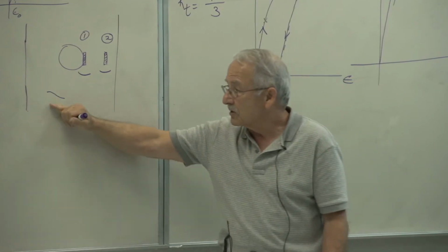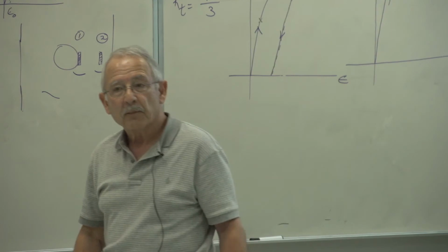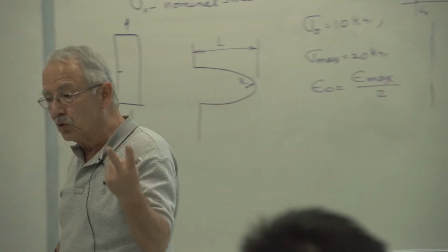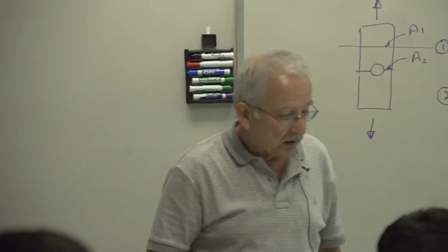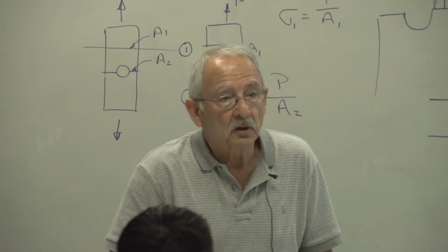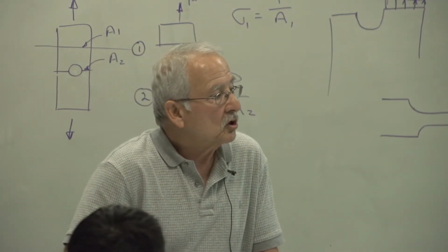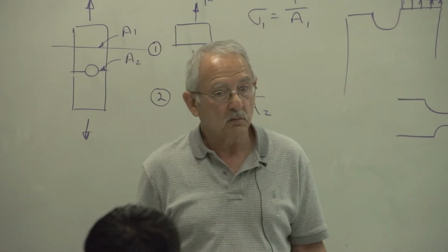So those stress concentrations are already there, therefore there's no need to use that. So these are the 2 cases where we do not use stress concentration factors. And again, remember that both of these are in static loading, a loading in which there is no speed associated with the load.